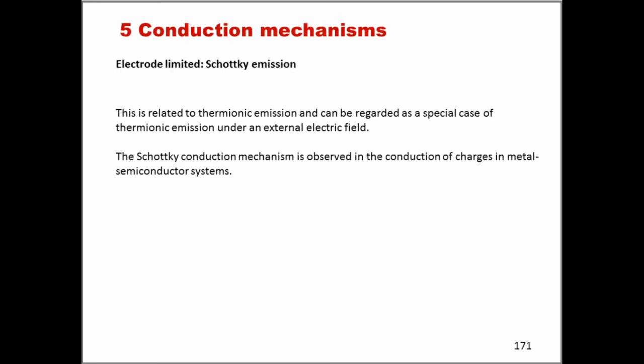Let us consider now another electrode-limited conduction mechanism, which is the Schottky emission. We have briefly mentioned this some time ago, as I said previously, when we were dealing with metal semiconductor contacts. And the Schottky emission is something that reminds really a lot of the thermionic emission. So it's a thermal process, if you like, but it is also field activated, and we will see this in a moment.